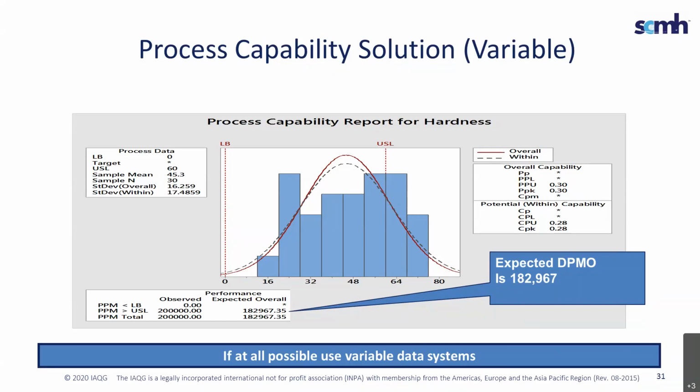And so I use those starting points of 20 samples, 25 samples. And then as long as it seems like I'm not getting special cause variation, then my original assumption is that I've accounted for my special causes. If I start getting it, then I start looking at what is it that's causing those special causes and try to adjust my sample sizes and rational subgroups to account for that, if that's going to be part of my normal process, or is it truly a special cause? So I just start with the 20, go from there, and start looking to see how my data fits into that original assumption.